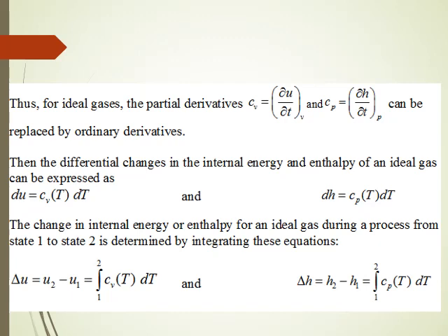Accurate analytical expressions for ideal gas specific heats, based on direct measurements or calculations from statistical behavior of molecules, are available, and they are given as a third degree polynomial in many good books. The use of ideal gas specific heat data is limited to low pressure, but these data can also be used at moderately high pressure with reasonable accuracy, as long as the gas does not deviate considerably from ideal gas behavior.